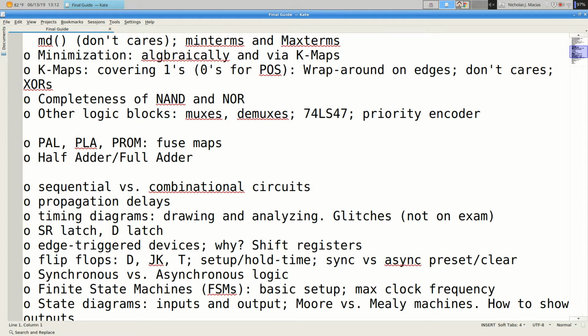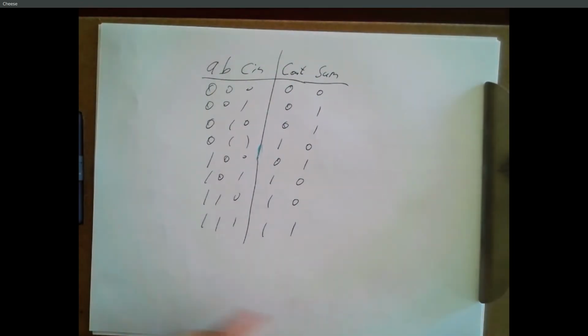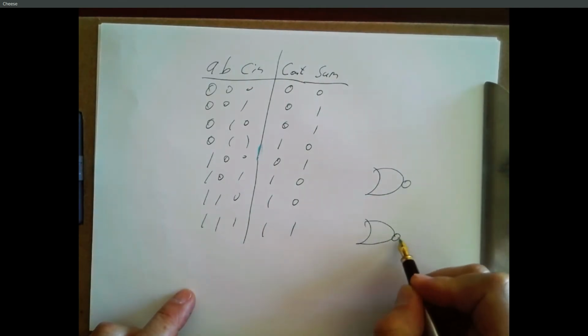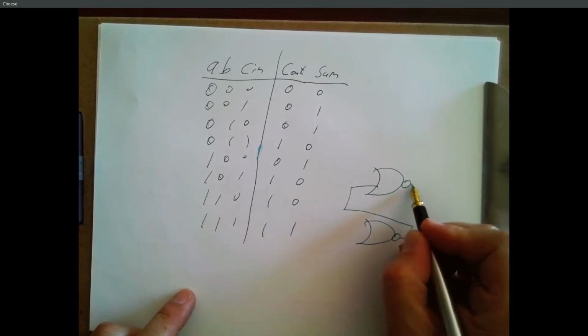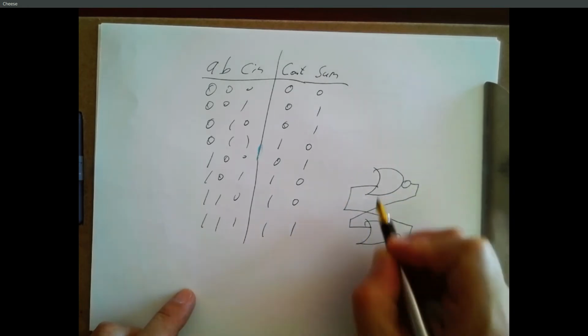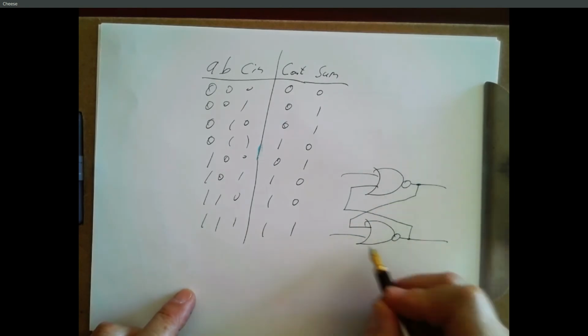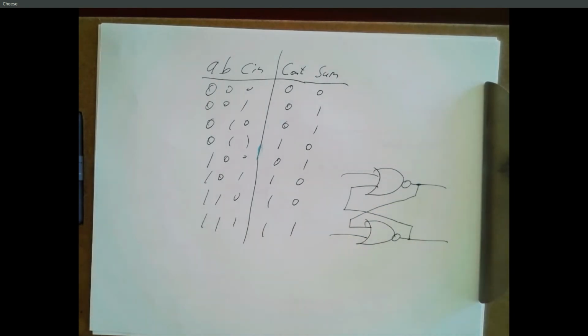All right, we talked about latches, and then we never did anything with them after that. But latches were the building block for what we did use, which was flip-flops. So a basic latch is typically a pair of inverting logic gates. And I always have to try it in my head to figure out which one would be set and which would be reset. But you just run through it and figure it out.